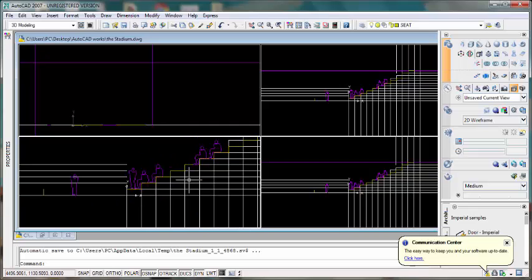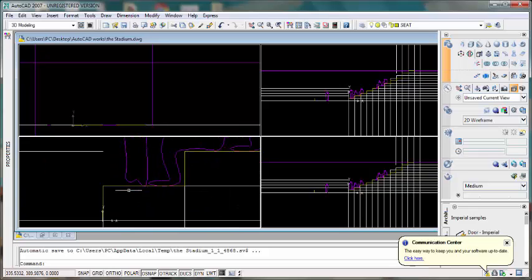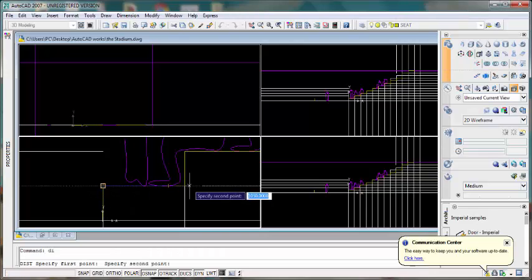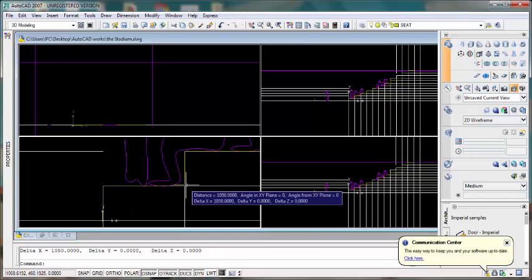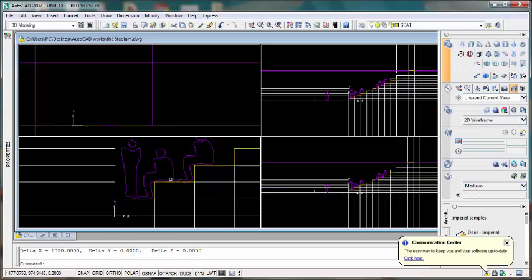Okay, so what you're just looking at is an intersection of vertical and horizontal lines. Meanwhile, using DI, this from here to here is 1050 millimeters. This is so that someone can sit here and not be disturbed by the next person's leg that is behind him or her.